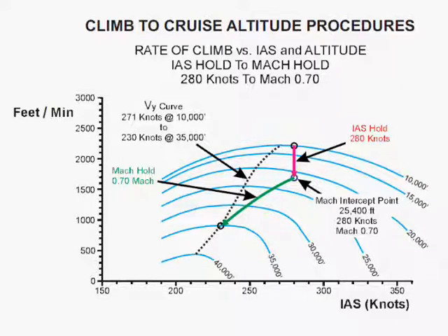During our climb at a constant indicated airspeed, Mach number rises during the climb. Since Mach number is the ratio of true airspeed to the speed of sound, this increase is caused by the true airspeed increase due to decreasing air density and the speed of sound decrease due to colder temperatures. Therefore, climbing at the indicated airspeed that is the best rate of climb speed at a low altitude, until reaching the Mach number that is the best rate of climb value at the cruise altitude, will produce climb performance that is very nearly equal to flying the more complicated best rate of climb airspeed curve.